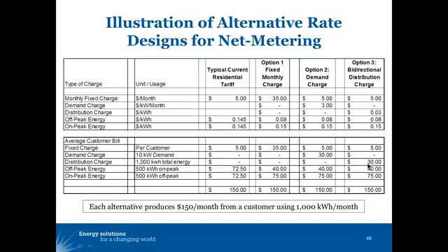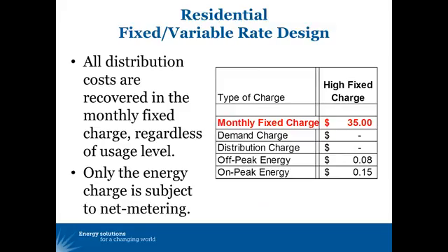And when we multiply these times the customer's usage patterns, the demand charge produces $30 a month, 10 kW of demand times $3 per kW demand charge, total of 150. In the case of the bidirectional charge, half of the energy, 500 kilowatt hours, comes from the grid, 500 is fed to the grid, so this customer is using the grid to move 1,000 kilowatt hours, and times 3 cents produces $30 in distribution charges, and a total of 150. So now let's zero in on these rates a little closer.